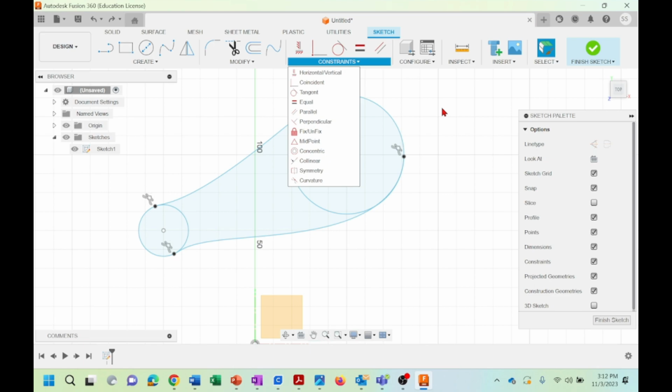These are the tools that help us have more complex designs in a much simpler way using these constraints, and they also help us have a more solid model. A solid model is a model where, if you change one size, the other sizes automatically change, not one where changing one dimension in one part breaks down your model.